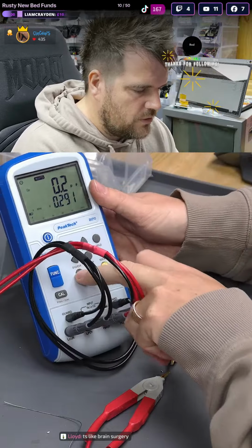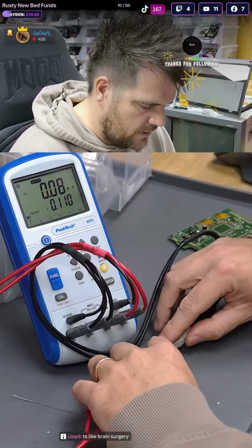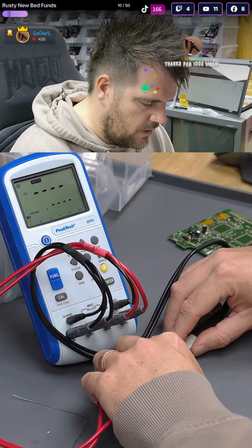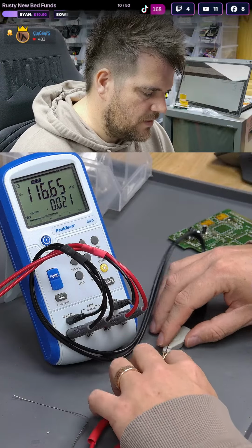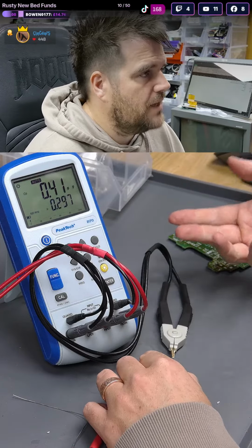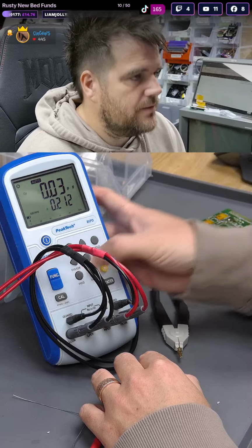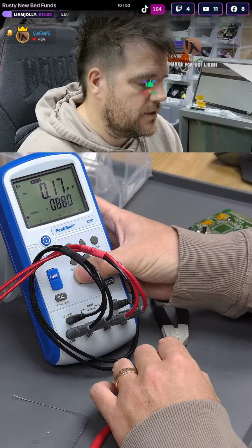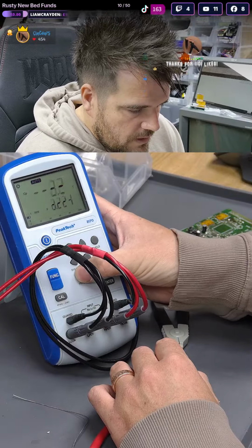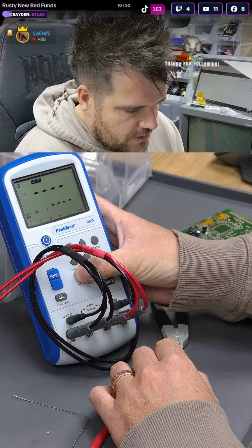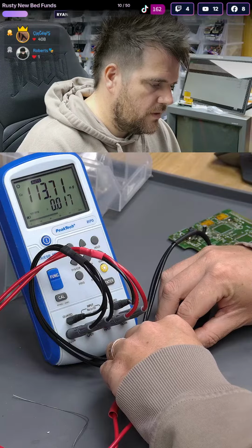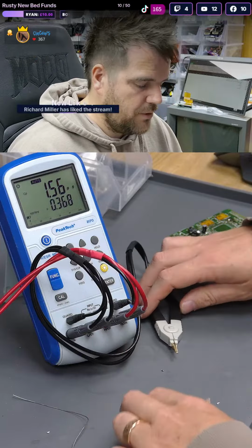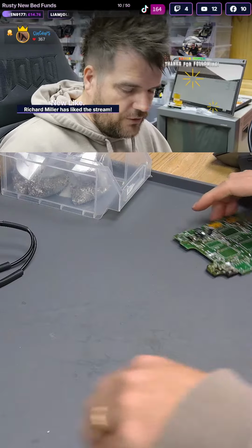I like to measure small caps, if you know it's a small cap, at 100 kilohertz. It's a nice average one, and it's what a lot of the tests will officially rate them at. So that's 116 nanofarad. My guess is that's a 0.1 microfarad. It's going to be 100 nanofarad and it's just reading slightly over, because the idea of 100 nanofarad is to filter out high frequency noise. I think 100 kilohertz is the highest test this goes to anyway, that's why it's tested at that. It's reading 0.11, but it's not going to be 0.11, it's going to be a 0.1 microfarad, so 0.1 uF. Very common, that's for filtering out high frequency noise.